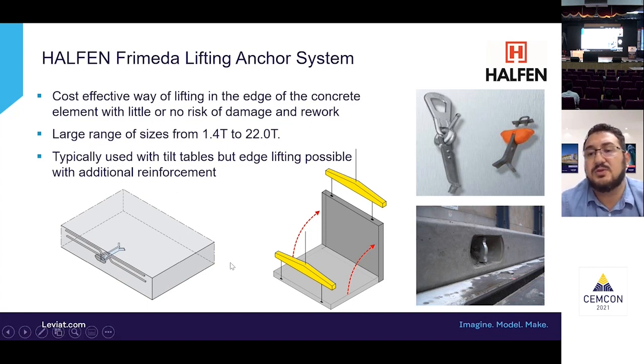But they can also be used for edge lifting, as you see on the bottom right here, where if a tilt table is not being used, you can still rotate the panel using these anchors. But we generally recommend additional reinforcement to strengthen that concrete edge and reduce the age of concrete that's needed before lift can occur.